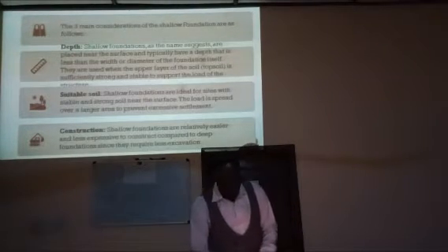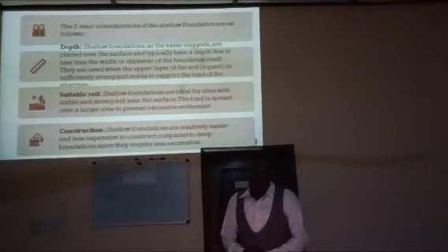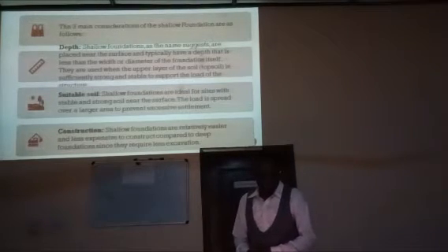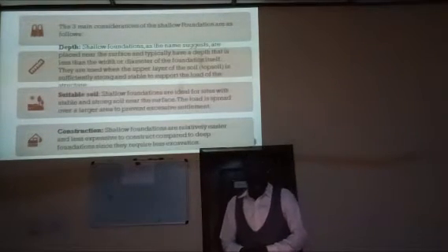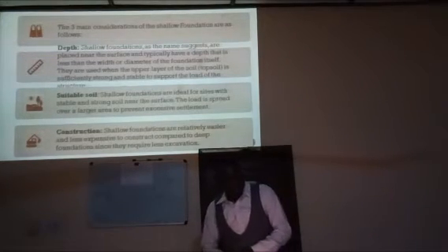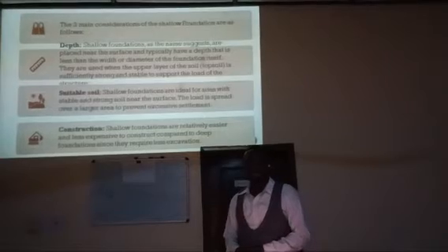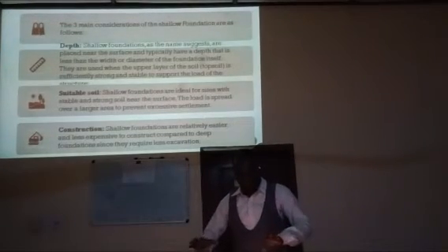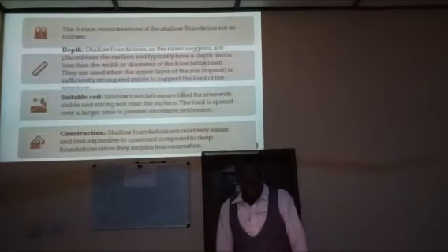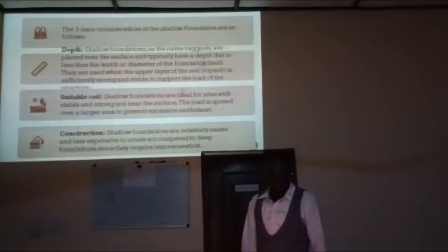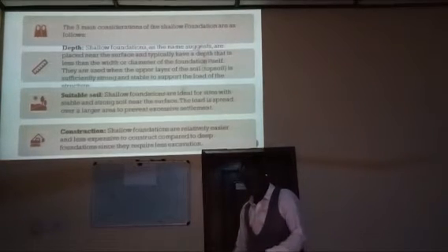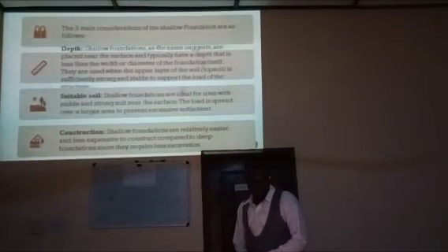foundation. Okay, number two consideration when doing a shallow foundation is the suitability of the soil, which I have already mentioned. So the soil must be ideal for the site, with stable and strong soil near the surface, such that the foundation can transmit and spread the load to the underlying soil. And the third consideration in shallow foundation is the construction methodology.